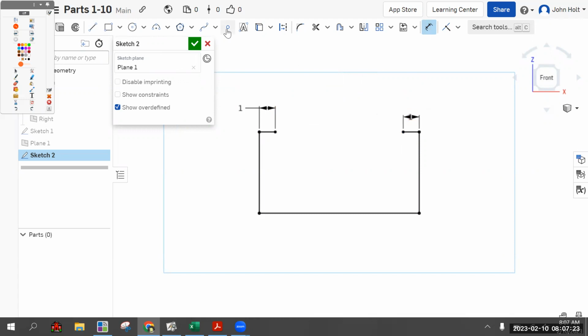And let's get a work point, put it somewhere close to where we want it, dimension the distance from that work point to the bottom, which is 1 also. And it's still blue because we still need another dimension. We talk about this almost every time: if anything's blue, it's not fully dimensioned, which it is because it moves left and right. It doesn't move up and down because we have that height dimension on it.